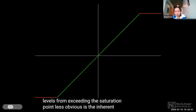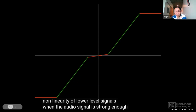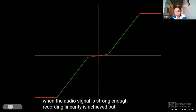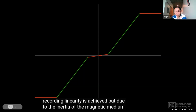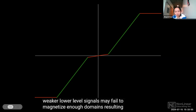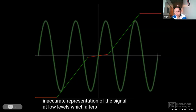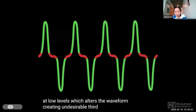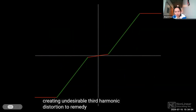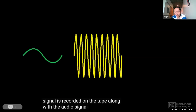Less obvious is the inherent nonlinearity of lower-level signals. When the audio signal is strong enough, recording linearity is achieved, but due to the inertia of the magnetic medium, weaker, lower-level signals may fail to magnetize enough domains, resulting in an inaccurate representation of the signal at low levels, which alters the waveform, creating undesirable third harmonic distortion. To remedy this, an inaudible, high-level, ultrasonic, high-frequency signal is recorded on the tape along with the audio signal. This is called the bias frequency.